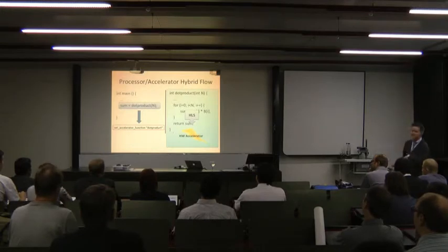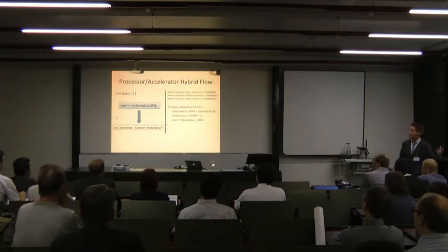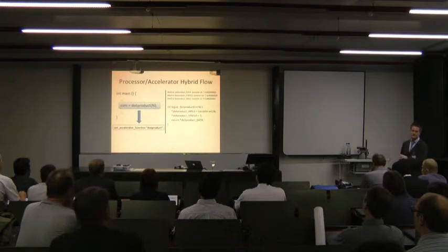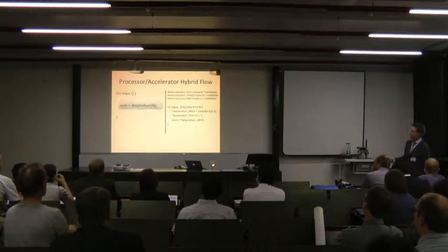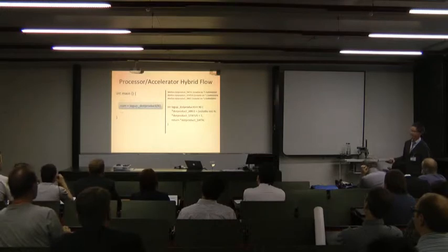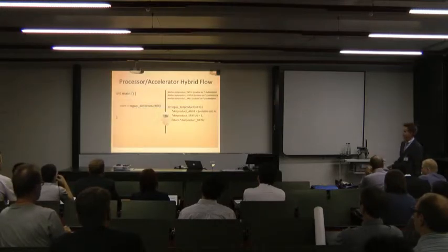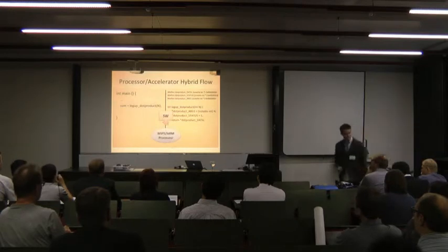Now the original version of that function is going to be ripped out and replaced with a wrapper. It looks like that, kind of gobbledygook. But these are memory mapped writes and reads over to the accelerator. Okay? And this new wrapper function, we call it a wrapper function, the original call to dot product will be replaced with a call to the wrapper function. Okay? And then this whole code right here is going to run in software on the computer. So all that will run on the MIPS or the ARM processor.